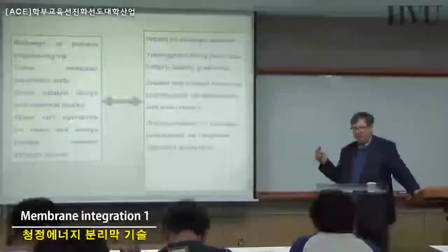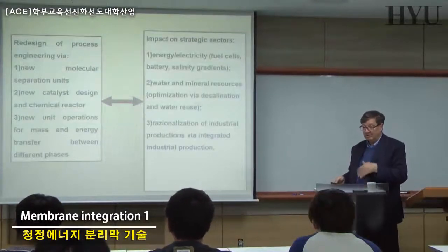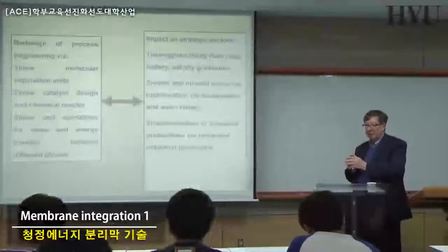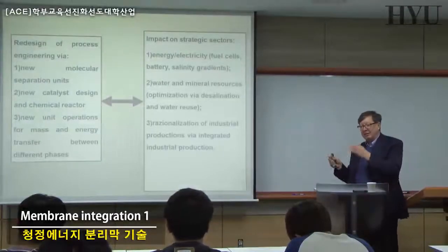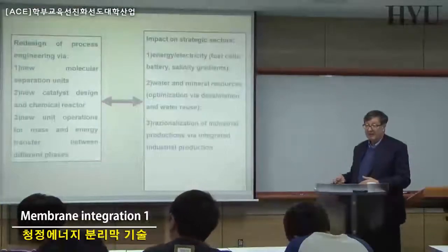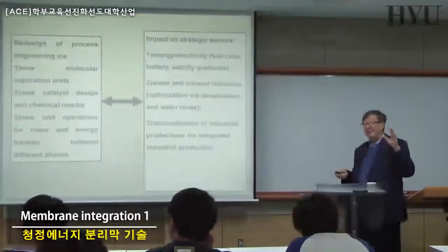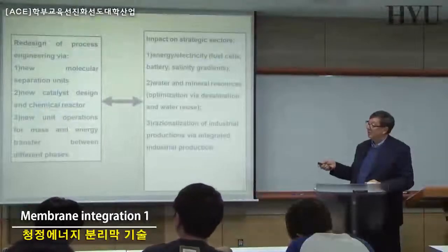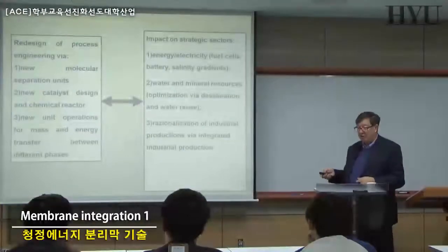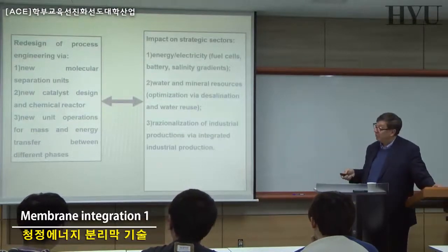Keep in mind that in any industrial process, in the running cost, not the capital investment, but for sure in the running and operation cost, separation sometimes covers 80% of the cost. The cost of the chemical transformation, etc., is marginal compared to the fact that at the end you have to separate different components. The cost of separations, in medical production, in biotechnology, but also in some other more simple areas such as textile or leather, can arrive at 80%. And today we have to control this cost for molecular separation. Reverse osmosis, that we have been discussing already, ultrafiltration, nanofiltration, electrodialysis are all the units that are useful for realizing this request, which is part of the process intensification.